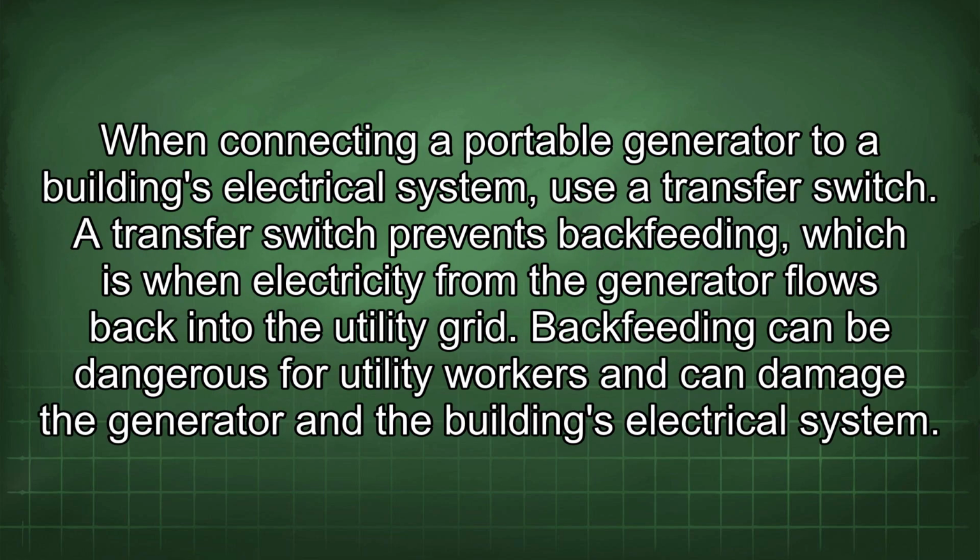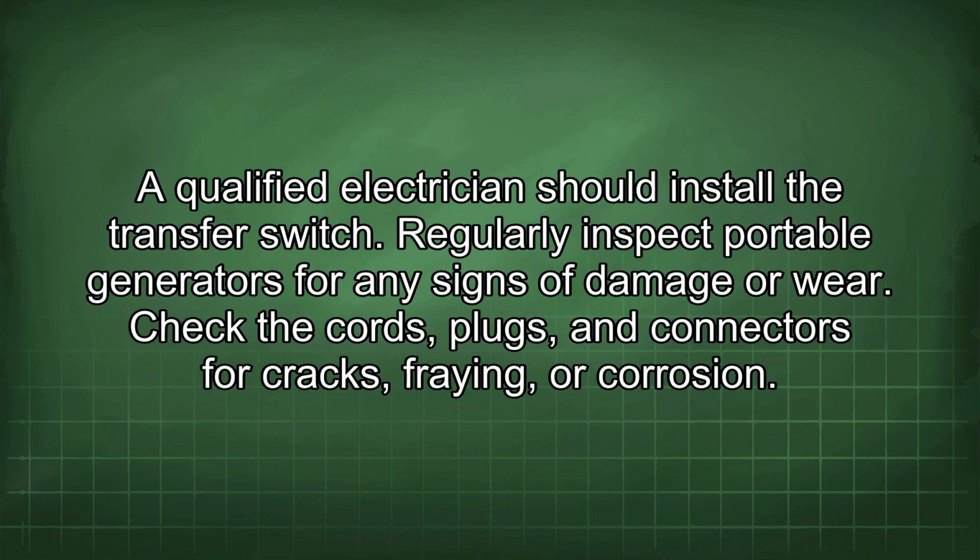When connecting a portable generator to a building's electrical system, use a transfer switch. A transfer switch prevents backfeeding, which is when electricity from the generator flows back into the utility grid. Backfeeding can be dangerous for utility workers and can damage the generator and the building's electrical system. A qualified electrician should install the transfer switch.